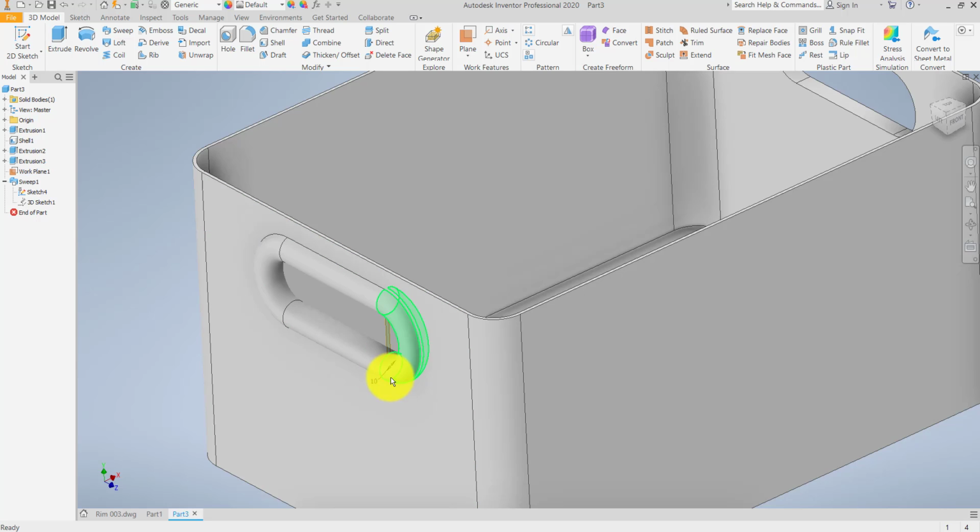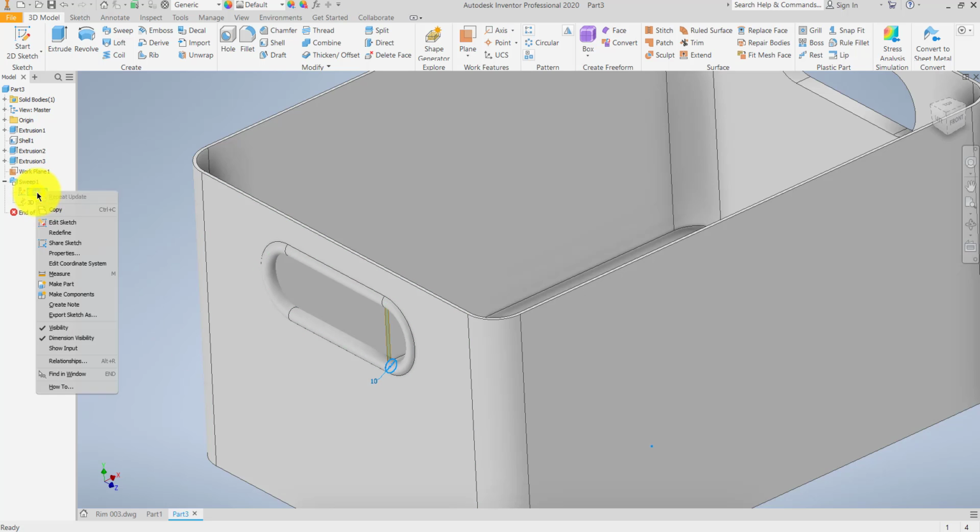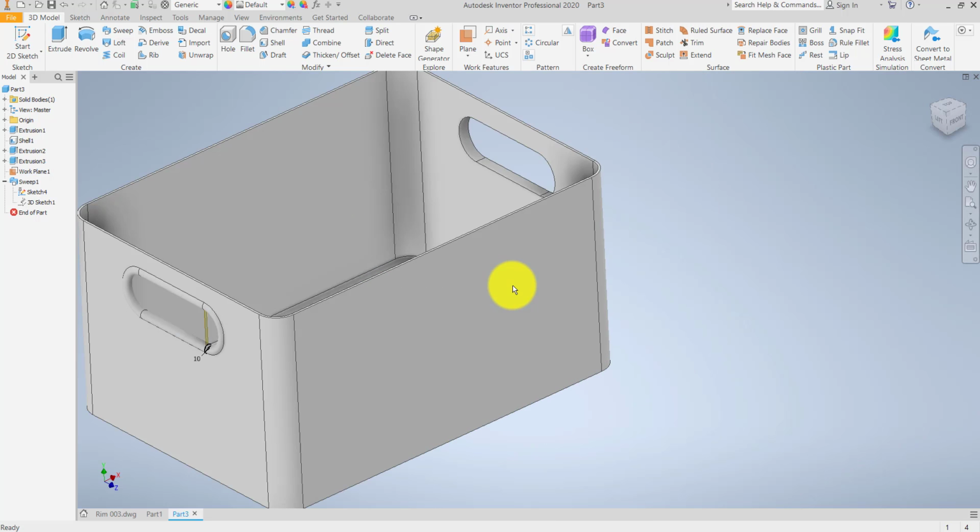And now it's not been updated. Even though you've changed it to 10, it's not updated. There's a tool here called local update. You could do that, and then right click and make this invisible. But for what I just showed you to work, the dimension must be there. So you must create a dimension.